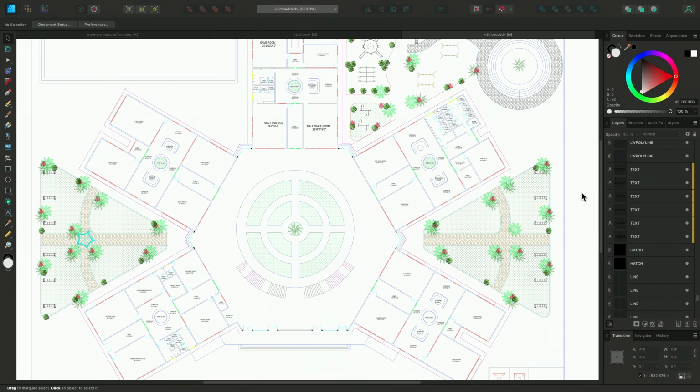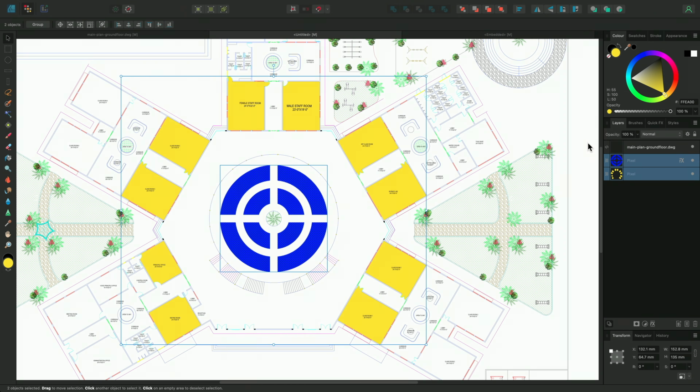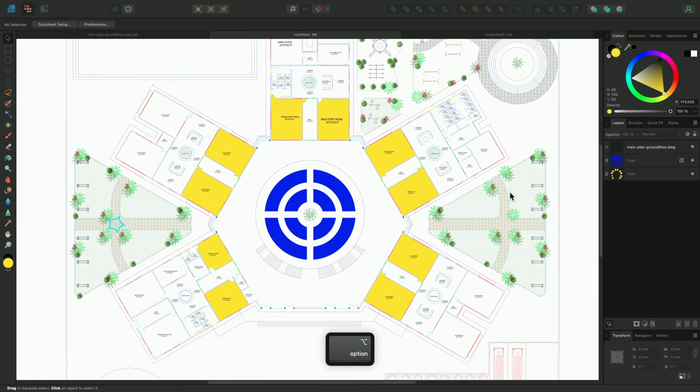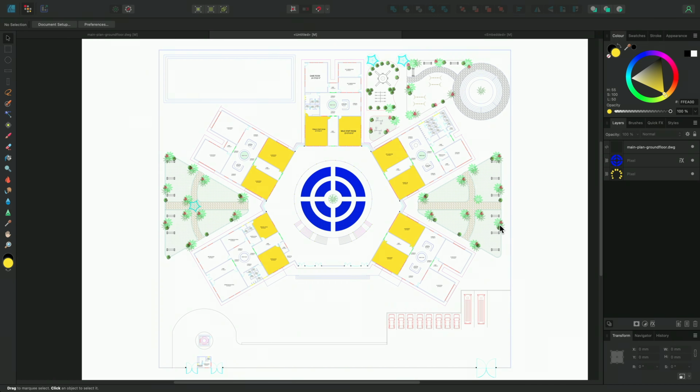And one of the major benefits to this workflow is that our color highlights and pixel layers are completely separated from our embedded or linked CAD file. So if this DWG file had some minor changes made to it externally and was then placed back into our file, all of our color work and other tweaks made in Designer would remain intact, and we can carry on working on the new file without any disruptions at all.